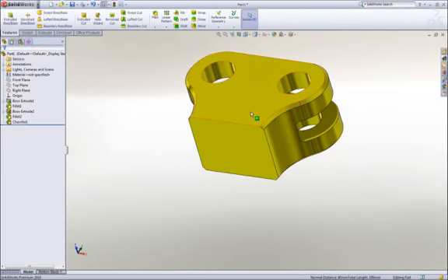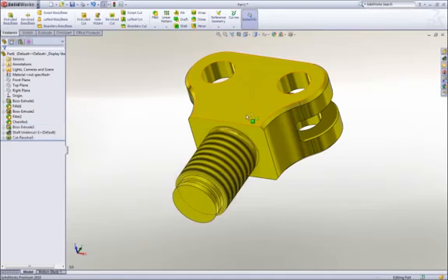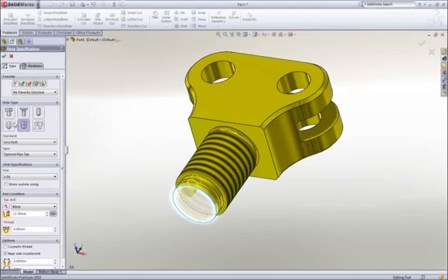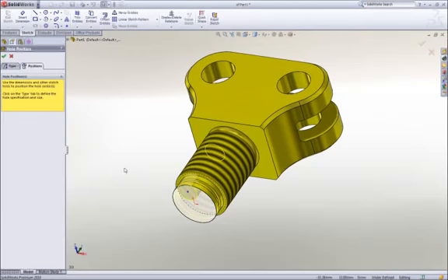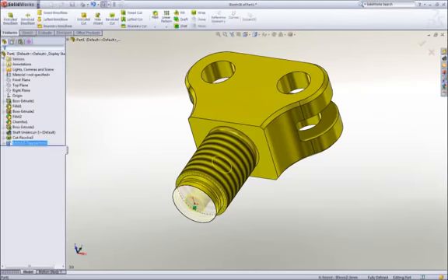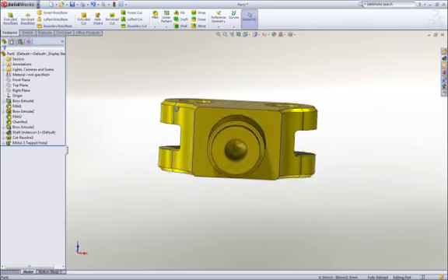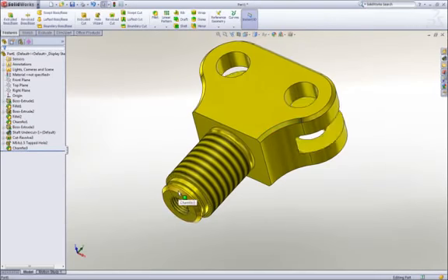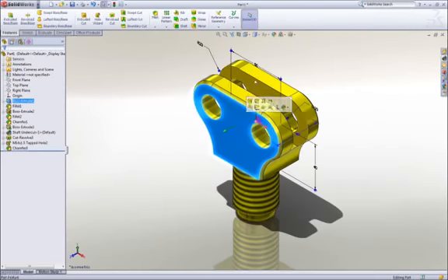Now that you have the hang of it, we will jump ahead a couple features and add a tapped hole at the bottom using the hole wizard. Gone are the days of looking up hole data, because all of the hole types, standards, and hole sizes are available. Choose the hole parameters, locate it, and SOLIDWORKS takes care of adding all of the proper information to define the hole. Let's leverage our previously created chamfer by dragging and dropping it onto the bottom edge to make a copy.